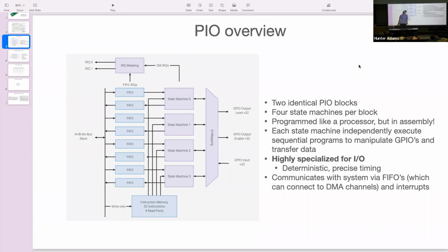That's really fast, and we could perhaps set up a connection to a VGA screen on some other microcontroller without using the PIO ports, but it's going to probably cost us a lot of CPU time. So maybe we could get the microcontroller to talk to the VGA screen, but you're probably not going to get a ton of Boids because you're probably not going to have that much time left over after you're done doing all this communication with the VGA to do interesting graphic stuff. We offload all the communication to these PIO coprocessors, and we spend all of our CPU time doing graphics.